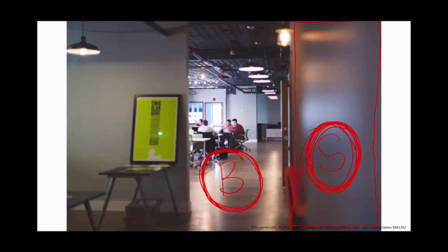Well, in a separated occupancy, the walls between the two occupancy types are going to have to meet that table, the number of hours that it's rated, and in our calculation of construction type, we can use one construction type for the B and another for the S. We can use sprinklers, whether it's sprinklered or not, for the B and for the S. So if the S has to be sprinklered, we don't have to sprinkler the whole building, we just have to sprinkler the storage area.